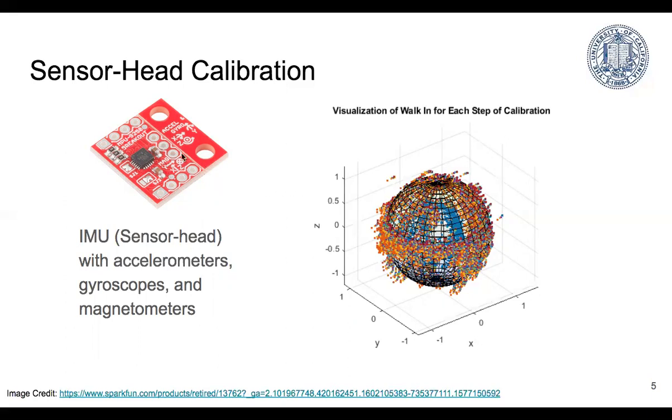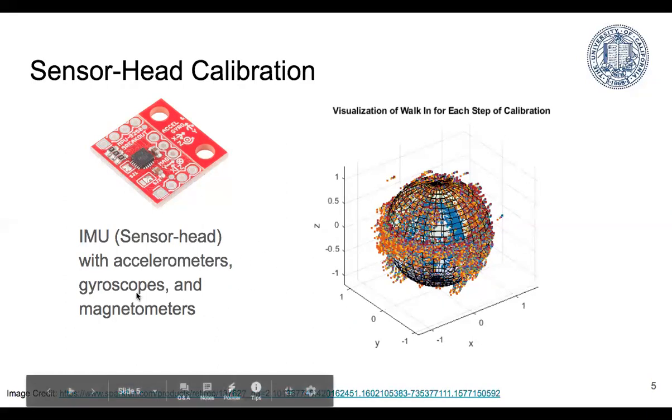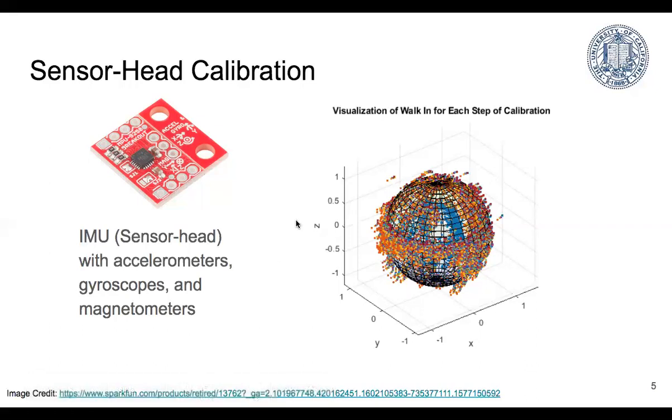Now, it gets a little complicated because some of the sensors, such as the magnetometer, might have a different orientation for their frame, where the x-axis is pointed opposite, or the whole frame is flipped, and that's something that you have to account for.